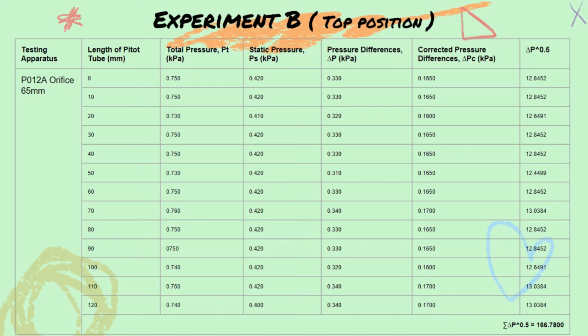The mass flow rate and average velocity are calculated too. To be taken note that the alpha value in the equation to calculate mass flow rate needs to be referred. Then, both orifice plate and venturi nozzle have their own formula to calculate the volumetric flow rate. Next, the data and results are tabulated as shown.